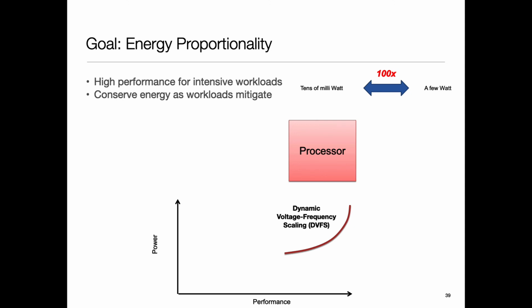So in this case, I have a big processor, and with dynamic voltage frequency scaling, let's say the performance-power curve looks like this. It's a big guy, so it has a higher baseline power consumption. So you see the curve is very high. It's just a schematic, but what I'm trying to say is there's a high baseline power, and then it's giving me a power-performance tradeoff.